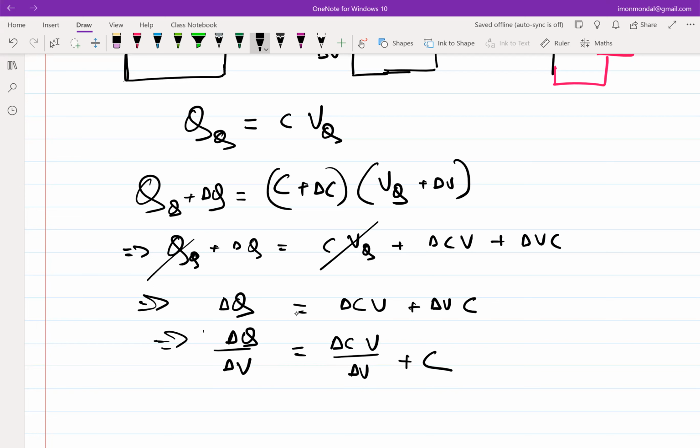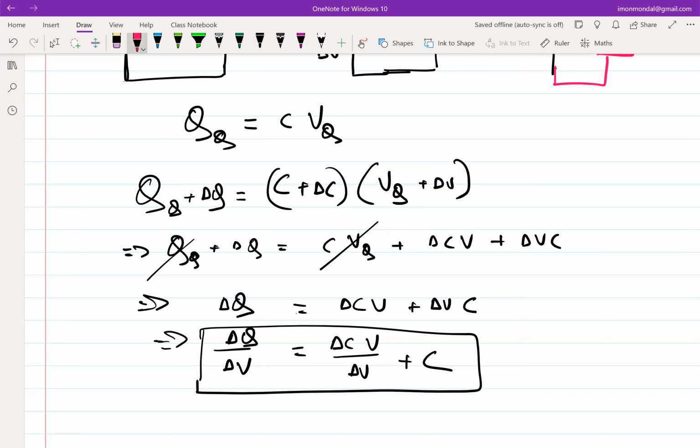So you will have to replace your nonlinear capacitance with this. You normally don't see these types of expressions because it doesn't give you too much intuition. So most simulators or even the literature tend to limit our incremental capacitance to this expression of del Q del V.